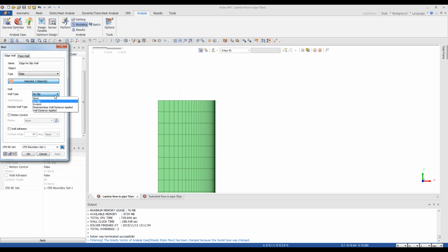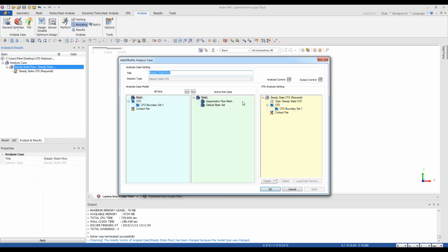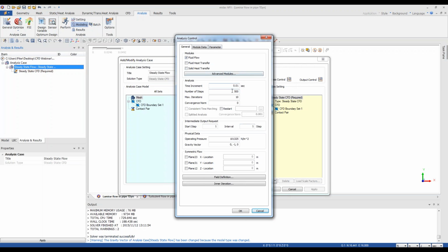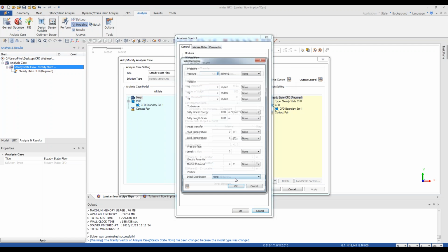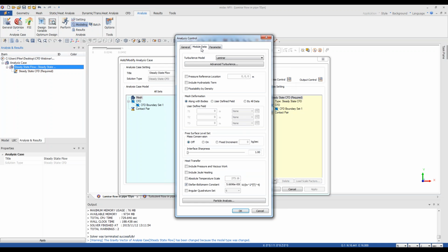And as I told you, I'm using this technique to calculate viscous sublayer manually. So I'm operating by the mesh. So that's all what I did. The last step is to go and edit, select the right analysis type. So in that case, this is a steady state CFD. I'm inserting following data, and of course there is nothing inserted in the turbulence, because my model, which I'm selecting from this, is laminar. I've calculated this Reynolds numbers, and this is very easy to guess.